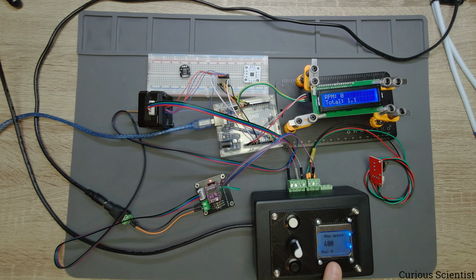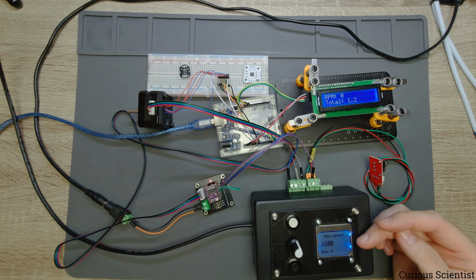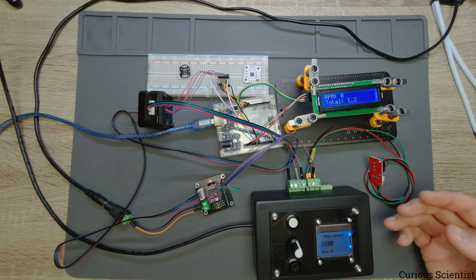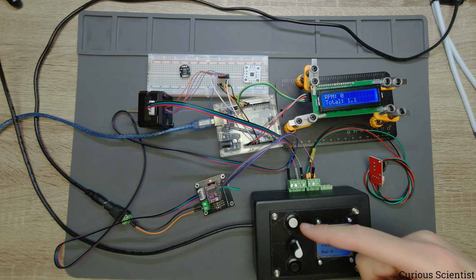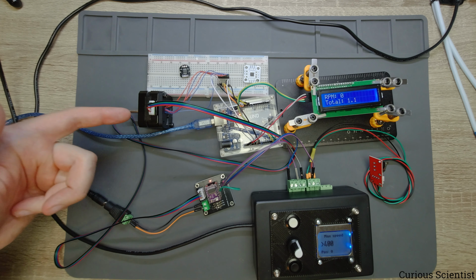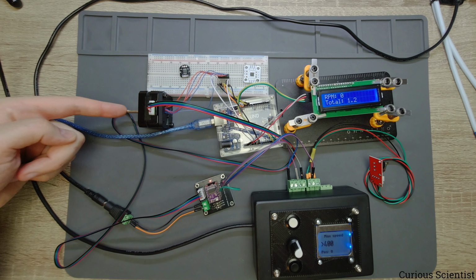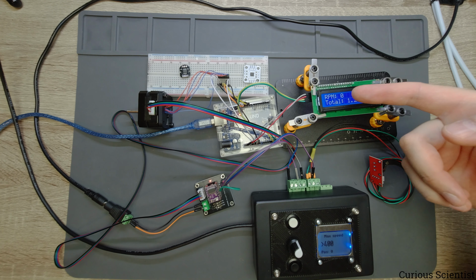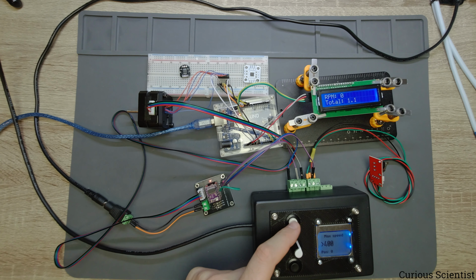So now what I have here is the speed menu. I entered it, and then all I have to do is just press this button and start moving the motor. So once again we will do 400 steps per second, so that will result in 2 turns per second, which is 120 RPM. So now I just start this and we will see what happens.